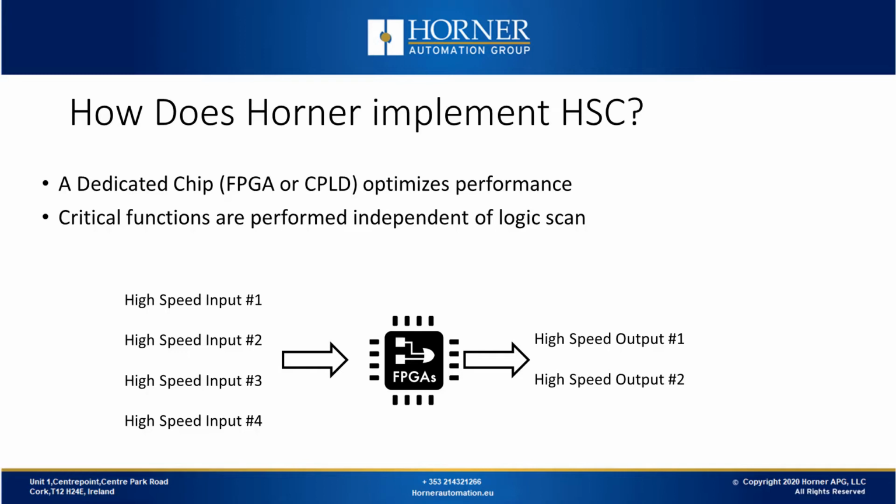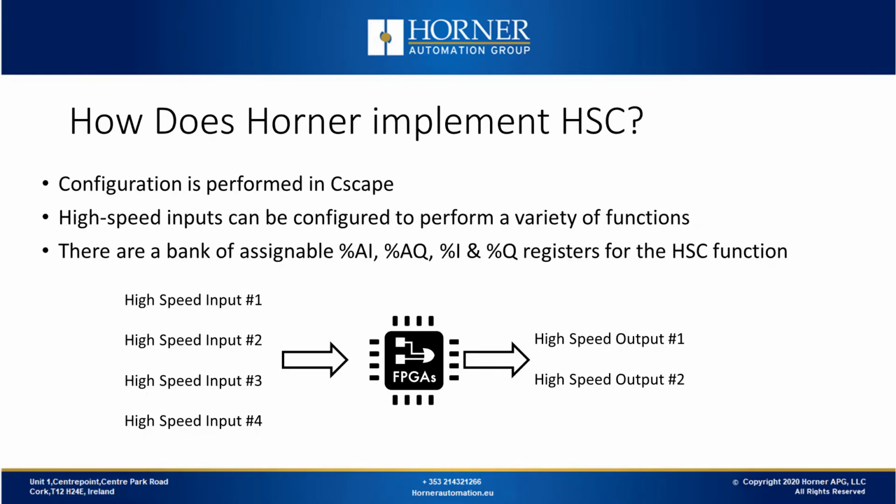We utilize a special piece of silicon, a component called either an FPGA or CPLD, and this is a dedicated part that handles all the high-speed input and output requirements for the application. It doesn't require time-critical signals to be dependent on the logic scan in order to perform their function of counting or output. Those high-speed input signals are wired directly into the gate array chip. The high-speed output signals are also wired directly into the gate array chip.